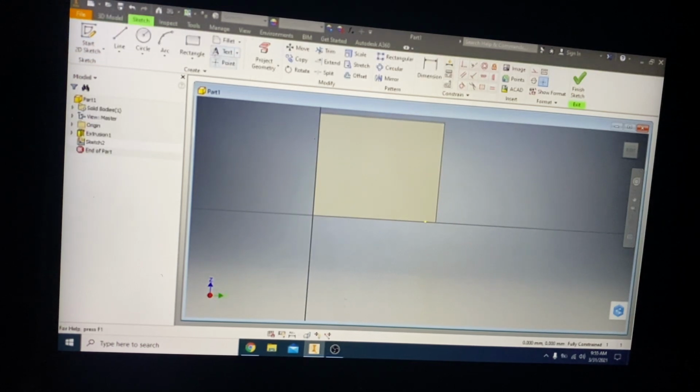Now I can go and draw a rectangle from there. Now see, it will select the end point. The point has become green. That means it has selected the edge of this block. So click there and come down. Now the blue block is active, so type 60 because I need to have height 60 and tab 20 because the width is 20. Enter. Now I have got the rectangle over there.